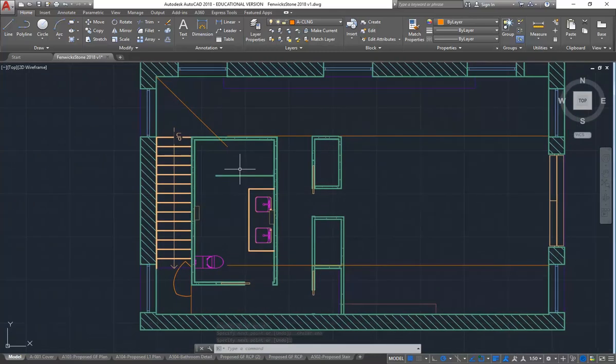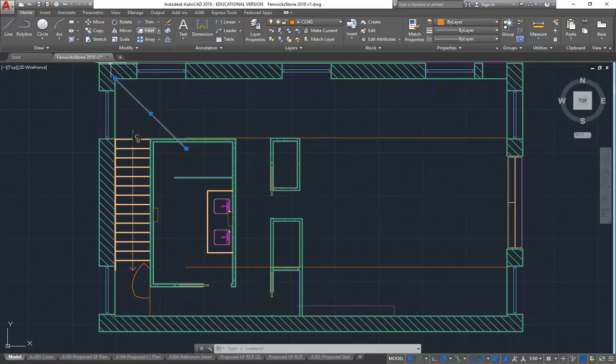Okay, so I'm not going to see it inside the bathroom here because again it's going to have its own flat ceiling. And so eventually I'd clear all of these interior bathroom fixtures and we just see the flat ceiling inside. So I'll delete some of them. And then this line here, which is again the corner of that raked ceiling, or the edge, that can also be mirrored. Now using any of these lines that give me the centre of the building. And then again I can trim using the edges of the wall here maybe.